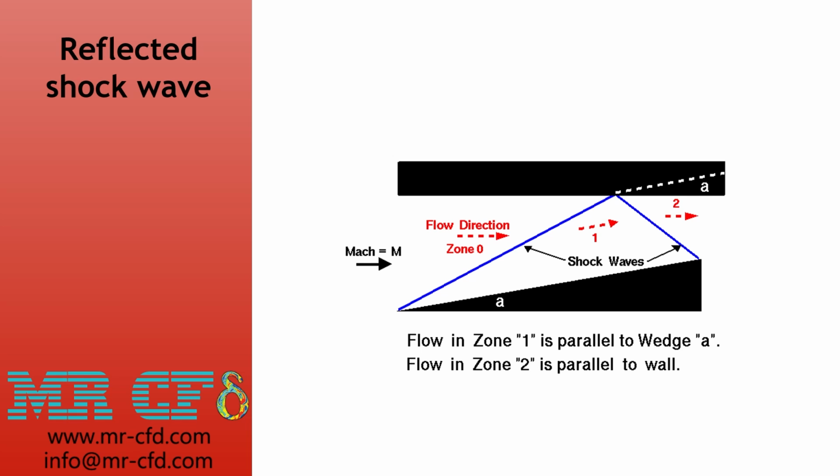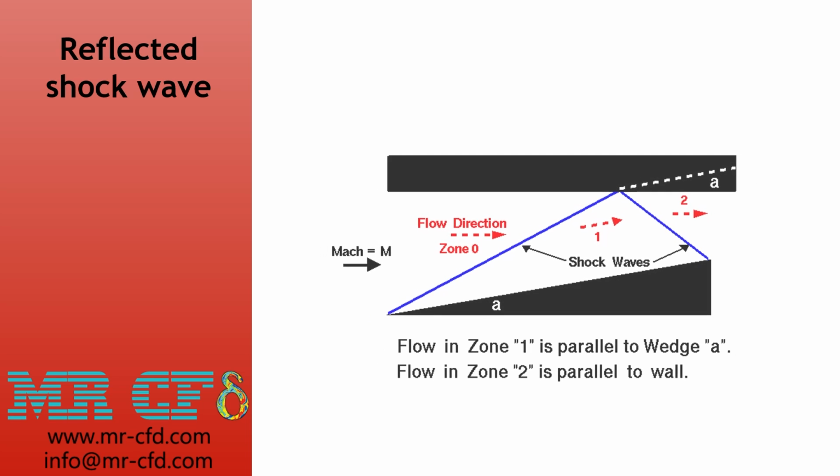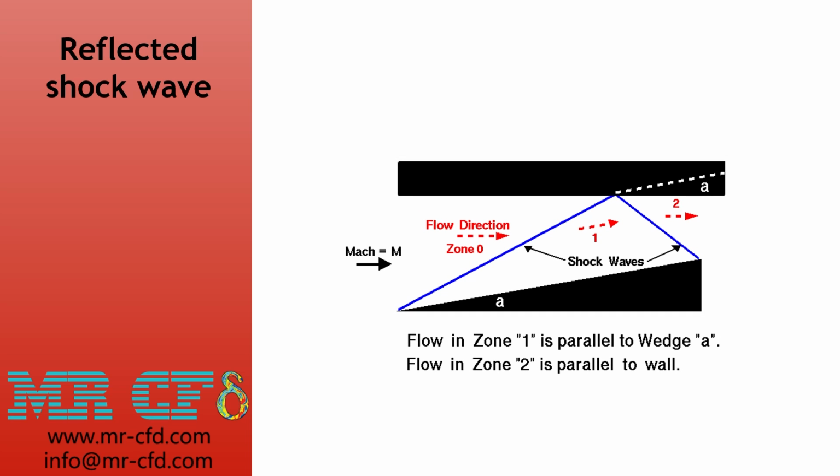So we can use this effect to reflect the shock waves and the flow passes each shock wave. As you see, there is a pressure drop after each shock wave. The velocity changes and drops until we reach our normal shock wave, and the flow after the final shock wave gets below Mach 1, and we have a subsonic undisturbed flow. And designing this reflection and the angles of it helps us to provide undisturbed air and analyze it.